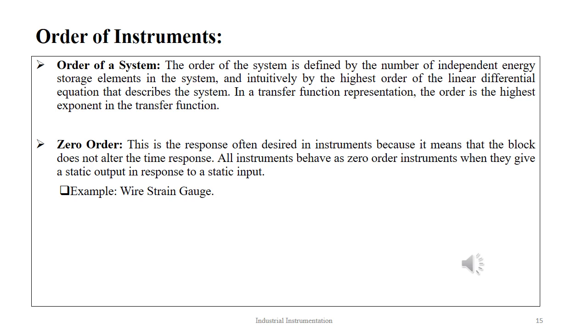Thus, to conclude, the order of a system is defined as the number of independent energy storage elements in the system, and intuitively by the largest order of the linear differential equation that describes the system. In a transfer function representation, the order is the highest exponent in the transfer function, as already illustrated in the previous expressions.